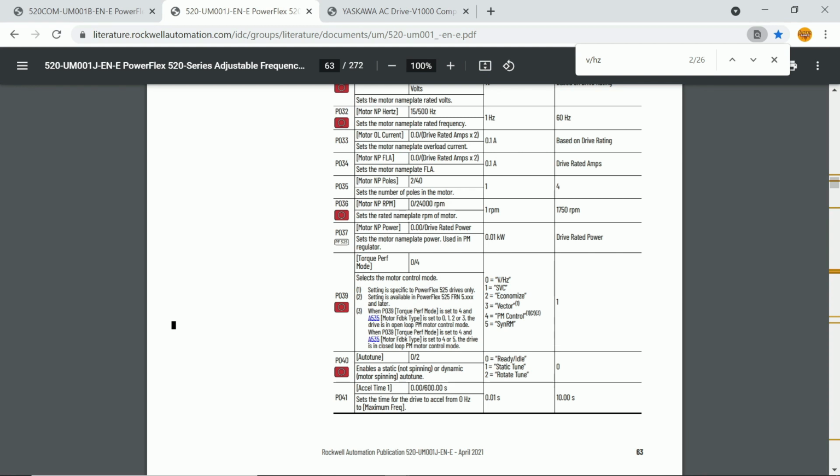Okay, so for the control part for permanent magnets and for the vector part, the one that they suggest is one without encoder, which is a direct torque, which is what we had previously seen. So this is the torque mode. Now, what type of application are we going to use? This is an important parameter, guys. If you have an easy application, leave it as such.